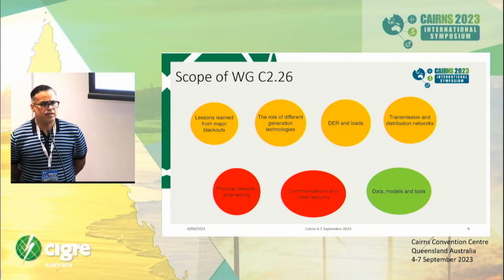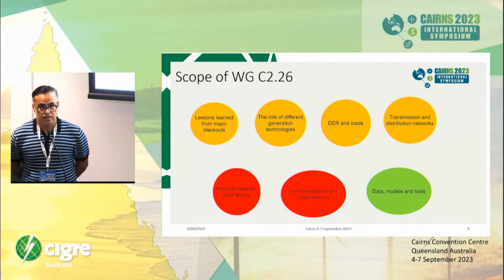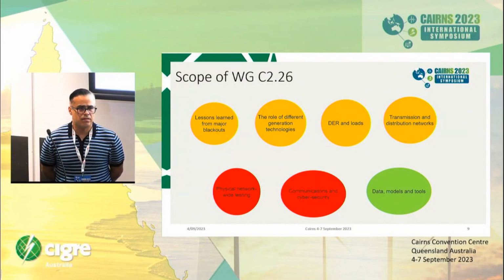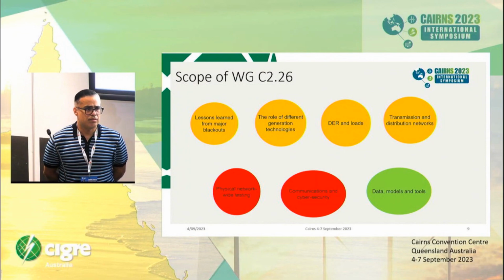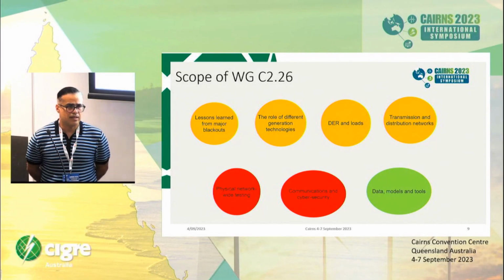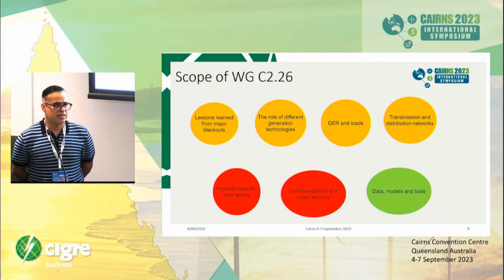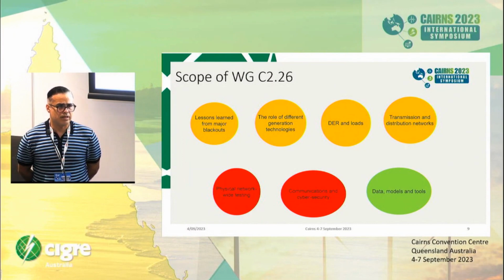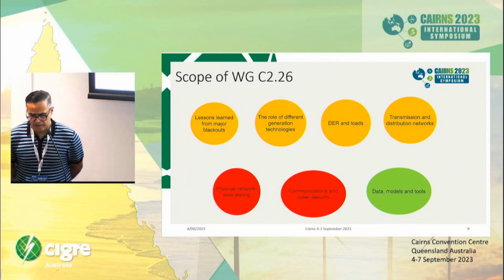Physical testing of the networks, especially looking at the wide area performance, not a single generator. We have many examples for synchronous machines, for inverter-based resources. And the key point is that these are the types of tests that involve multiple components in the power system, not just a single element. And there are some contemporary tests, for example, using grid-forming batteries to energize a wind farm. And these are real power systems. They're not like microgrid or lab tests, so they're all real power systems.